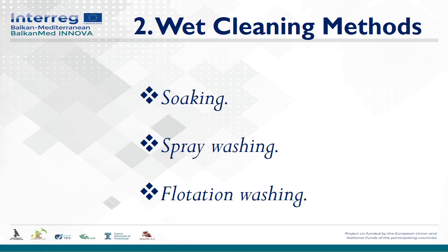When dealing with highly sensitive products such as berries or salad that need to be cleaned even internally, it may be helpful to use sparging air through the system. Using hot water or including detergents improves cleaning efficiency, especially when the contaminants are mineral oil.